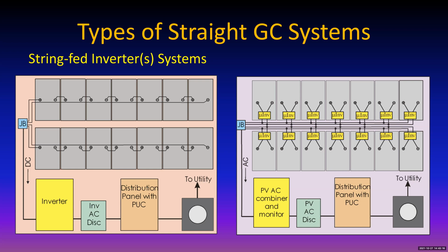The one on the right is a microinverter system, and you'll notice that's a bit different. Every module has its very own microinverter. These microinverters, the most common ones are rated at about 290 watts, and they connect directly to the inverter, and they connect in parallel on the way out. Now, the significance here is that if you're going to connect sources in parallel, they have to be current sources, not sources of voltage, but sources of current.